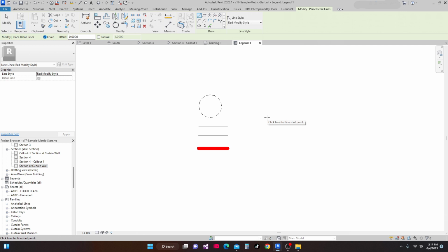Now let's talk about this Draw panel. The Draw panel contains a number of geometry tools to draw within the active view. The tools allow you to create lines, rectangle, and this is inscribed polygon, and then circumscribed polygon, circle, and this one is start-end arc.